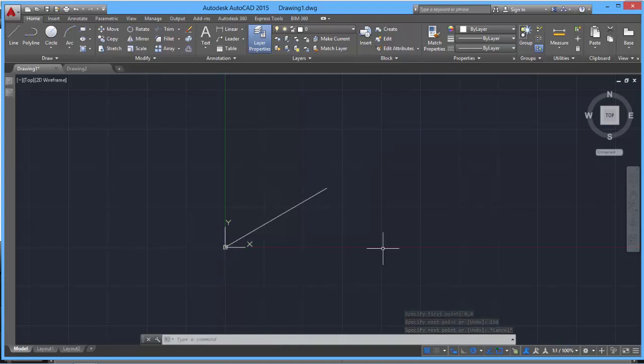The x-axis is the start of everything, and it moves in this anti-clockwise direction. So all the angles are reading anti-clockwise around the screen. So that's how to draw a line. So it's click and click, but you could also draw a line from the end of this point and then come down 30 degrees at 150, enter, and that should take your line back down to this x-axis.